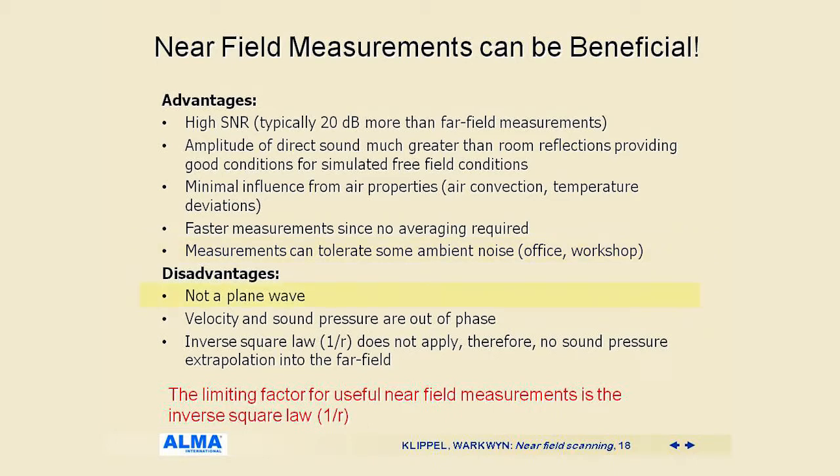Disadvantages: it's not a plane wave. The sound velocity and the sound pressure are out of phase. And the inverse square law does not apply. Therefore, you cannot extrapolate the sound pressure into the far field. This is the main limiting factor, the inverse square law.